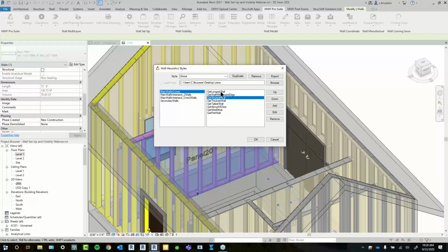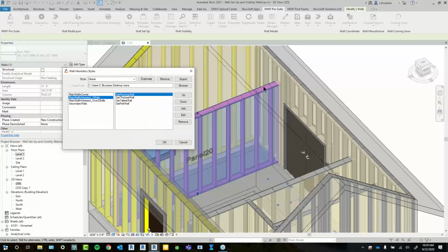So if you did want the longest wall, instead, you can start moving these configurations around. It activates these buttons. And you'll be able to move your priority list around. So I can take the longest wall now. Same thing with T-intersections. We always take the running wall as the main wall, but you can always change that priority list. And this is going to be, of course, project-wide across all of your joins.